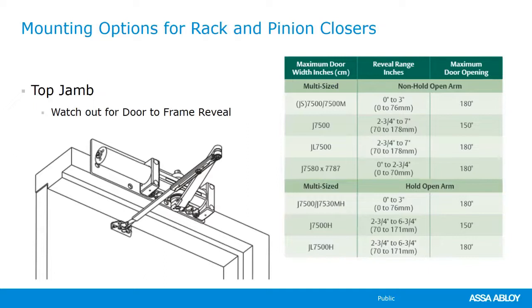Yeah, so are those measurements for the specific door closer, or are they generic? So they are very specific. Every single door closer model that I have ever come across has different templating. Even sometimes arms that are in the same family. And this especially goes for parallel arms. When we get into those here in a second, you really have to pay attention to the door closer model.